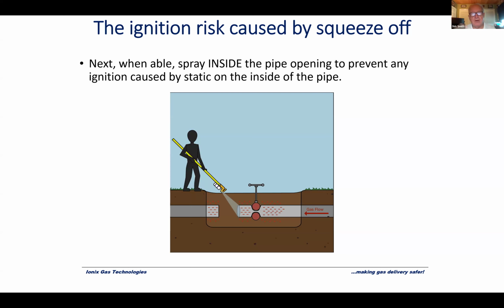And again, if you have a bell hole and you've done the squeeze off, how far down the static is generated from a squeeze off, nobody's done any research on that. I really can't tell you. But it's better to err on the side of caution.